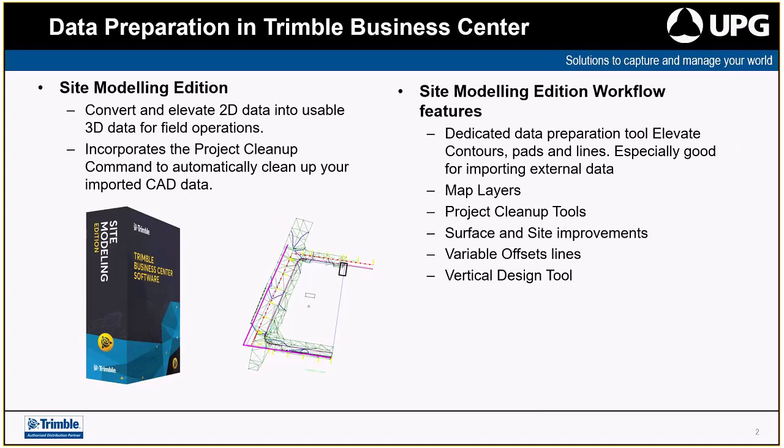It also incorporates a function called the project cleanup, which will automatically clean up your data, removing unwanted layers and a few of those other bits and pieces that can be quite troublesome when you're getting third-party data from somewhere that you don't really trust, or it's in different layering conventions and it's all over the shop. I don't know how many times I've had that in the world of surveying.